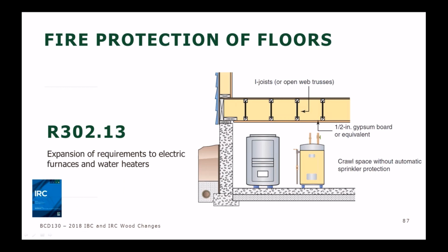No worries. We get that question a lot, and because carriage bolts are fully threaded and not yet covered under the ANSI standards that we refer to in the NDS, the prescriptive provisions that we develop in DCA 6 would not necessarily cover carriage bolts.